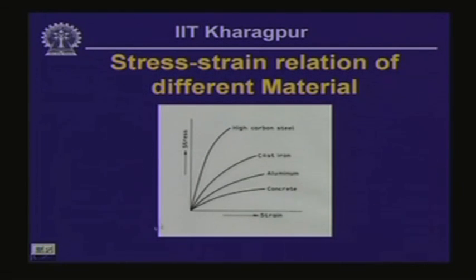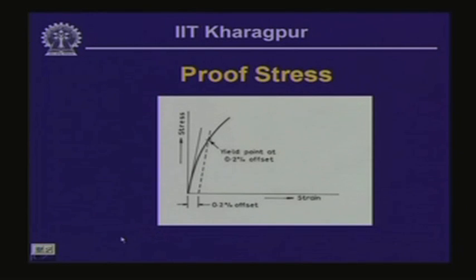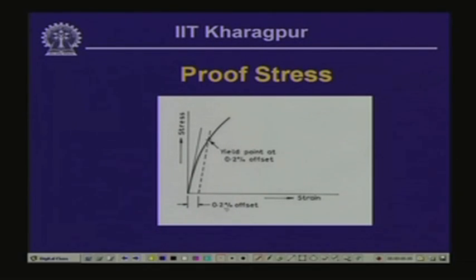Now, to compute the value of yield stress, it is observed that the strain corresponding to the yield stress value is of the order of 0.2%, which is 0.002.